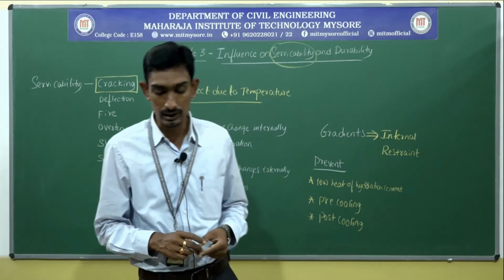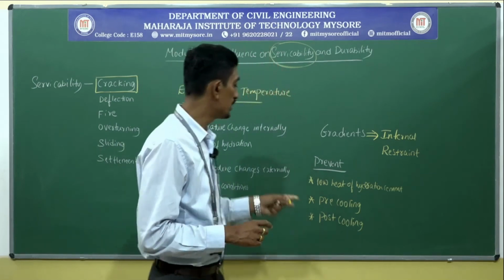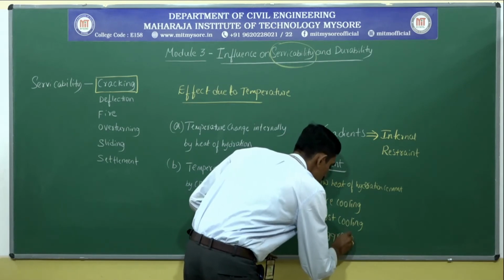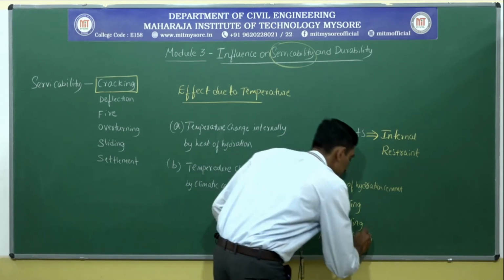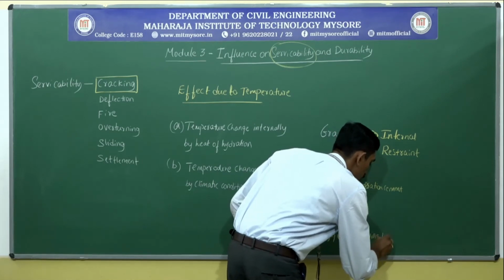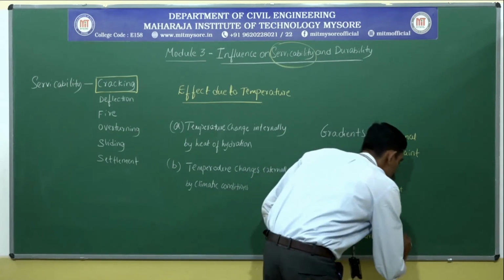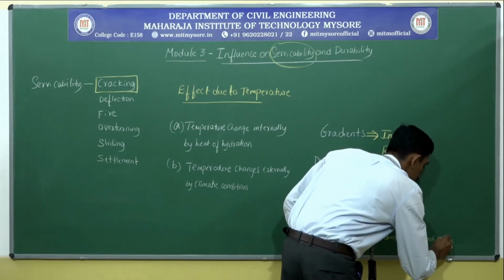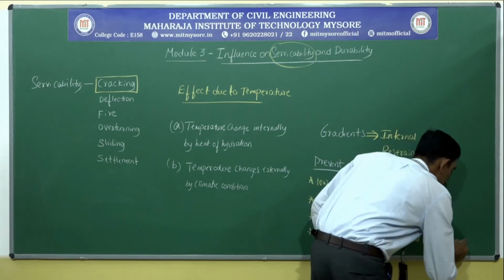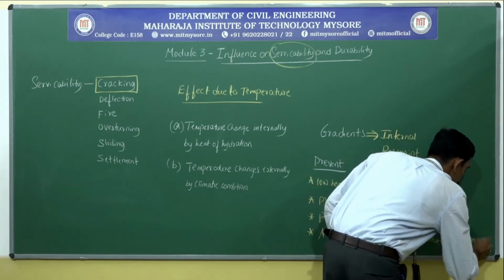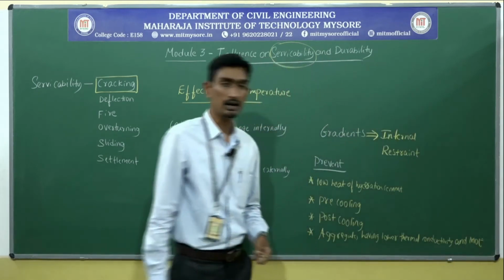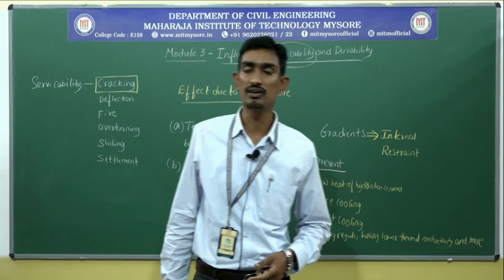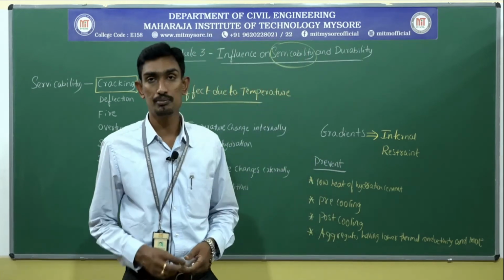And one more method is using aggregates having lower thermal conductivity and lower modulus of elasticity. With aggregates having a lower thermal conductivity and lower modulus of elasticity, we can reduce this problem.